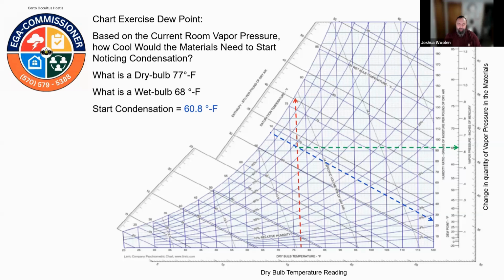When there is a difference in the vapor pressure, nature will seek equilibrium, right? So we know that when we come to a drying loss, if we simply open up the door and put a fan there, it will draw out the greater amount of moisture because it's seeking equilibrium, right?